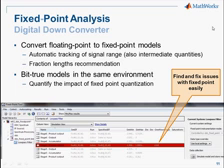So let's recap what we saw in the Simulink HDL Coder demo of FPGA design using MATLAB and Simulink. We saw how we could start with a floating point model in Simulink and how we could compare it with a fixed point model as we prepared for hardware implementation. We showed how the use of data logging with a fixed point tool could be used to diagnose issues with the fidelity of the fixed point model. Then we saw how the fixed point tool assisted us by proposing changes in word length and precision, resulting in a fixed point model that captured the required fidelity without making the design larger than necessary.